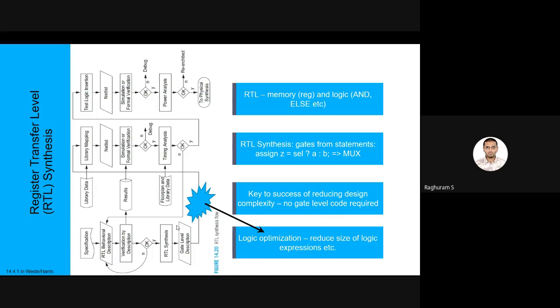That particular step is called logic optimization, and there are many methods. The K-map is a method of logic optimization. The next level of K-map is called the Quine-McCluskey method. Then there are other, even more complex methods, called two-level logic optimization. There are tools like Espresso which do logic optimization. There are many things going on before the actual netlist is ready. Logic optimization is the second last step in front end VLSI design, so we're still in the front end part.